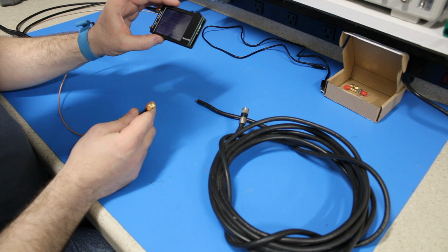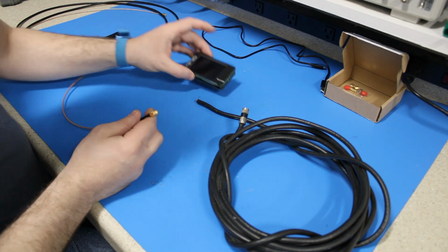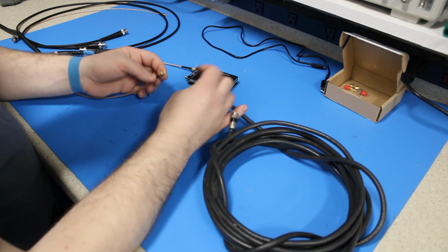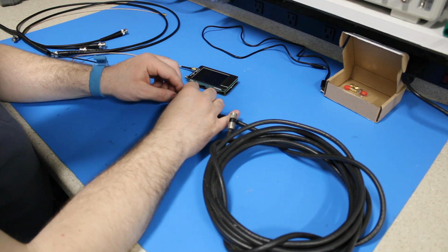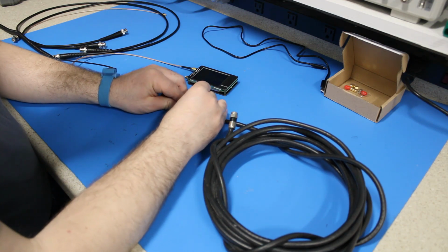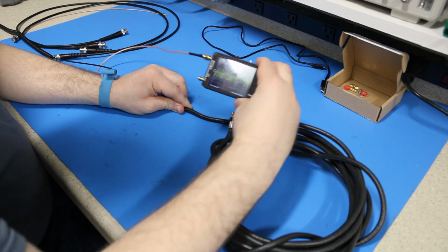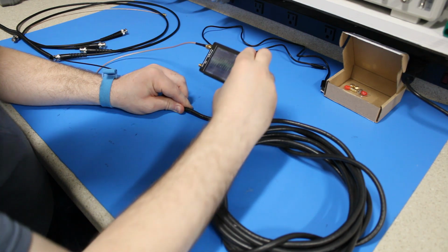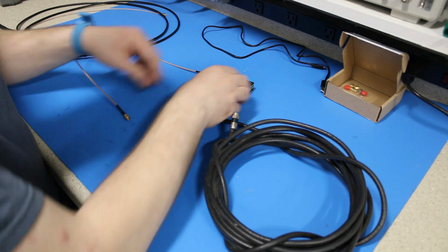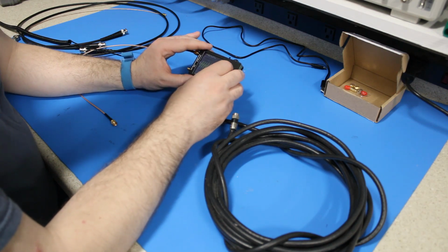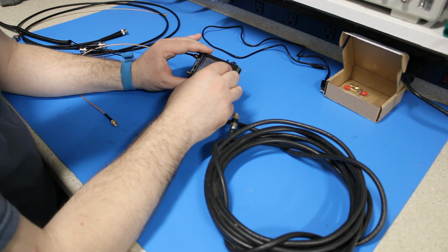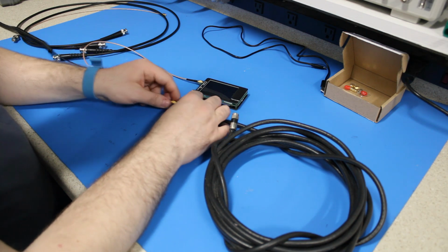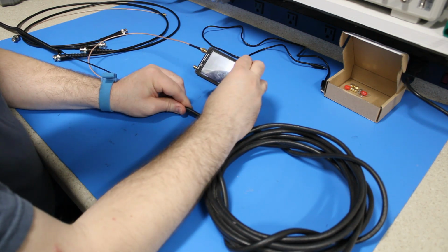Now in this case I have a stimulus set from 50 kilohertz to 900 megahertz. I know for a fact that's going to be too high, and in this case I don't have a connector on this end, so I'm just going to physically push them together. You always want to watch out for any reflections that this could cause. And if we look at the phase plot, there are a whole lot of cycles on the wrapped phase. So I'm going to adjust the stimulus to be a much lower frequency. We'll say maybe 100 megahertz on the top end, and we'll see where that gets us. So we'll take a measurement right there, and what do we see?